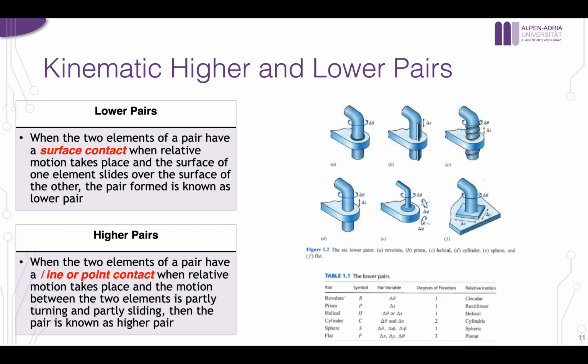First of all, we have 2 types of actuators or motors. These actuators could either rotate or slide, which is called linear actuators. And we don't have one motor or actuator that can do rotation and slide at the same time. Our goal in inverse kinematics, or kinematics in general, is to control these motors, of course.